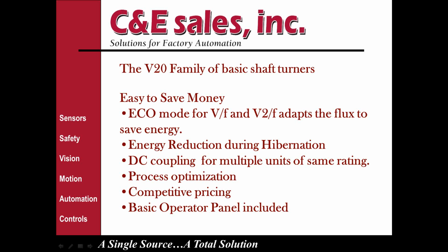There's some process optimization. You do have PID loop controls and other features that are normally used to handle process analog inputs and analog outputs. And it's very competitively priced. The V20 is our low-cost leader for applications. But again, it's intended for standalone applications, not for networking, not for tight integration into PLC systems.